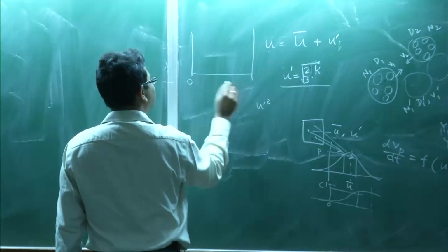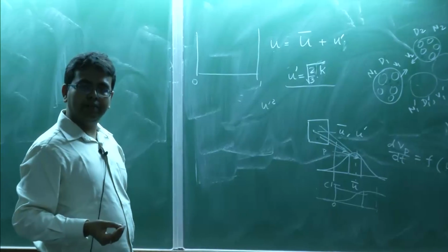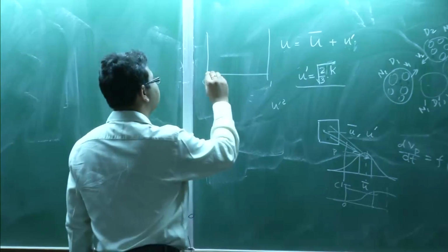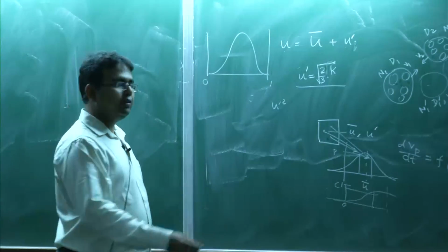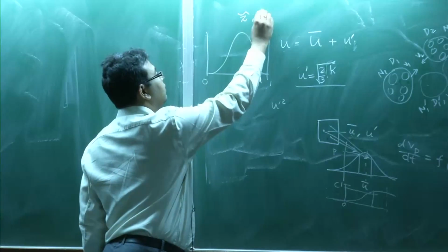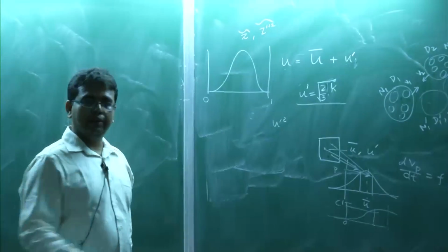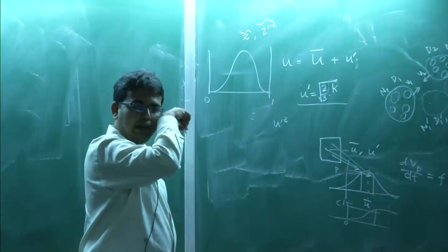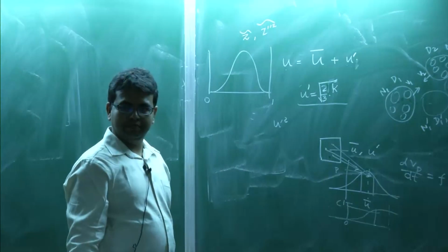So, between 0 and 1, we can plot the PDF, probability density function of mixture fraction. Let us say it is like this, okay. This will satisfy some mean and some variance that you have computed already in your CFD code, and from this PDF we need to identify a mixture fraction.